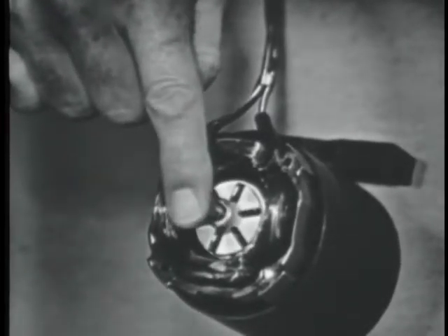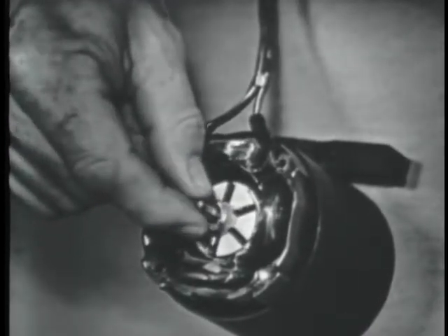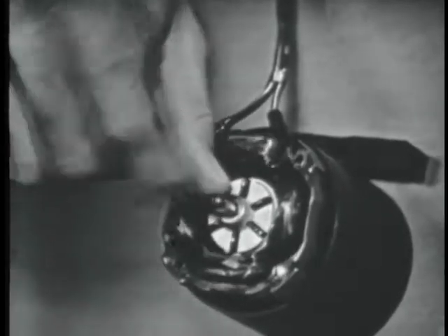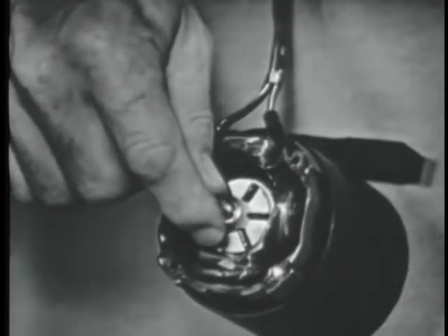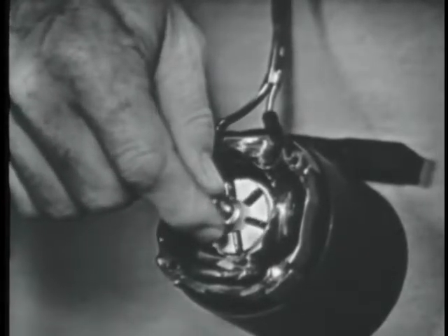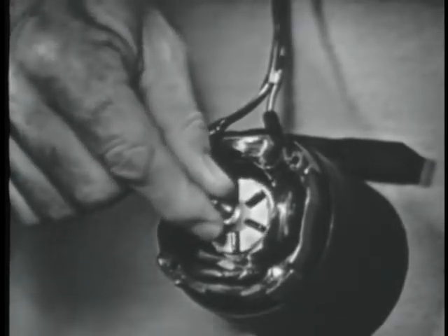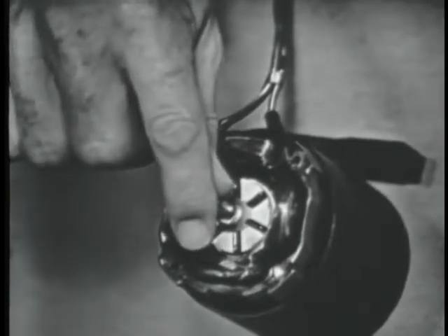Now, there's a limit to this. I thought there would be. For example, if I make the load on the motor too great, as I'm doing here with my fingers, it stops. But the magnetic field is still zipping around there, right? Right, nothing slowed it down. No. So the frequency of cutting has gone way up. Now, from this, you might think that the current in the rotor, when I've got it stopped like this, has also gone way up. But that's not so.